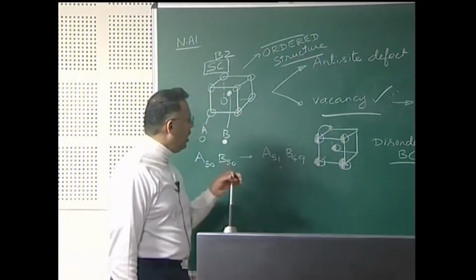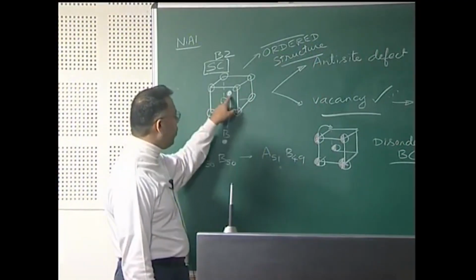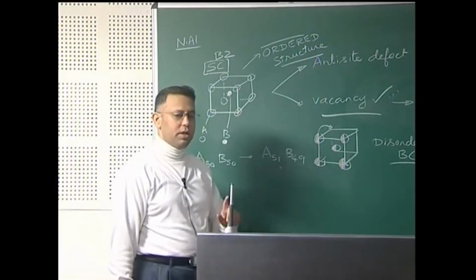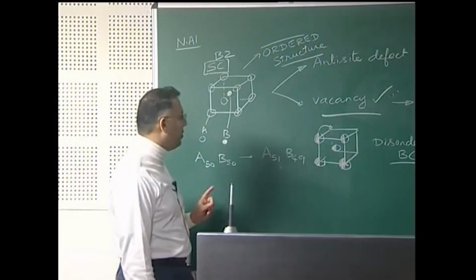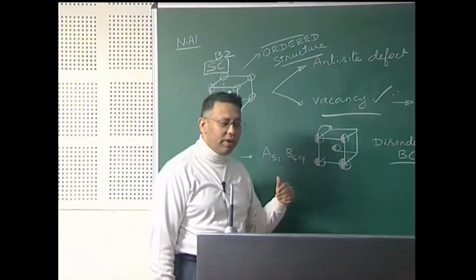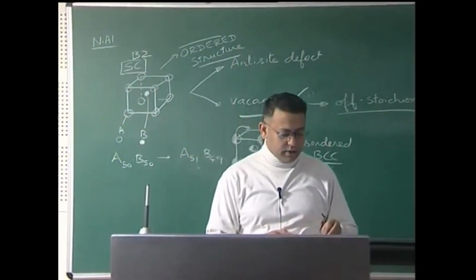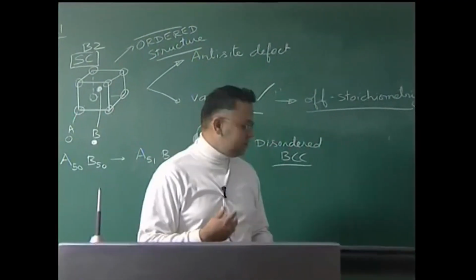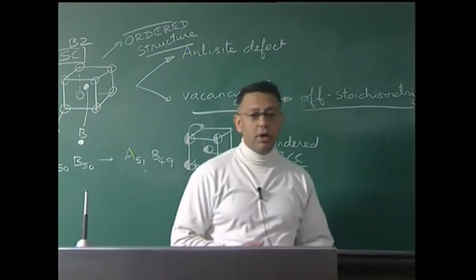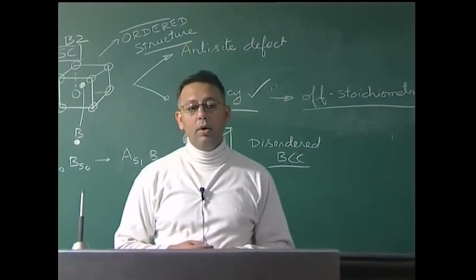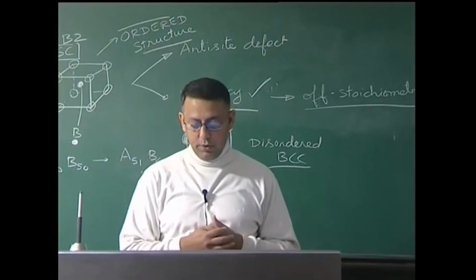On the other hand, this structural vacancy is localized to one of the sublattices, it is not randomly positioned anywhere in any of the sublattices, and the very fact that this vacancy is a structural vacancy makes its role in diffusion different from that of a thermal vacancy in diffusion.